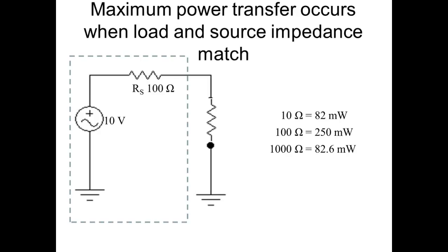Because you can hook some speakers in series, but what you're trying to maintain is the output impedance of the radio, which the specs will tell you. So you're going to hook some of them in series. Now the voltage is going to be shared, but the sound quality is going to be better, right? You've heard these people before. They play their radio real loud and it's all crummy, with all that distortion. Either they're overdriving their amplifier or the impedance of their speakers and the amplifier don't match.